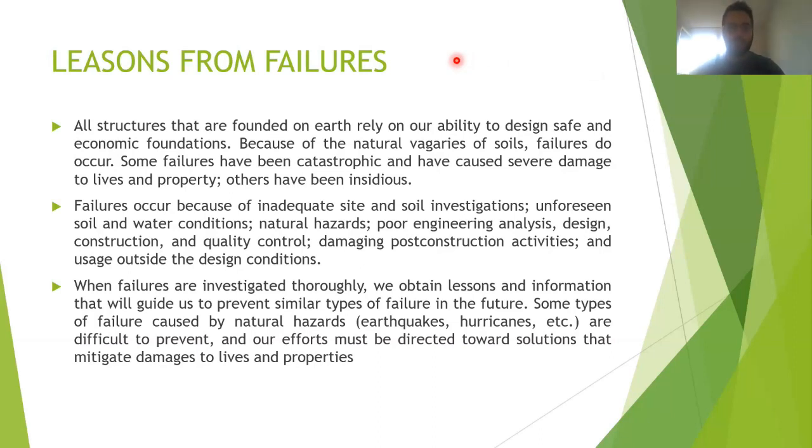Failure occurs because of non-integrated site and soil investigations, soil and water conditions that you couldn't recognize, natural hazards, or poor engineering analysis. That's on you. Also design, construction, and quality control. The quality control is also on geotech engineers.